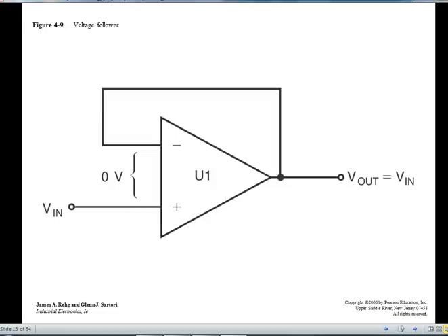Yeah, you want the nuclear weapon to blow up. Let's say I've got a very delicate signal over here. So I've got some antenna, and I've got some itty-bitty current coming off that antenna giving me the voltage difference. I go through a voltage follower, I add power. The voltage out can now have watts of power associated with it, whereas the input signal may not have had any power associated with it at all. It may have been some communication thing that is very fleeting in nature. So I can have a voltage follower.